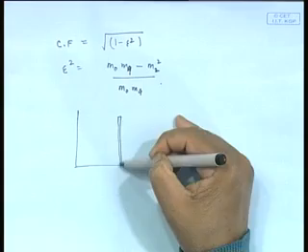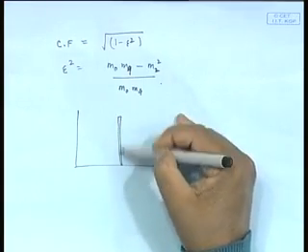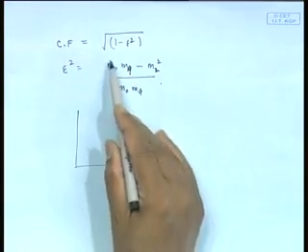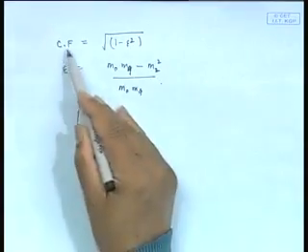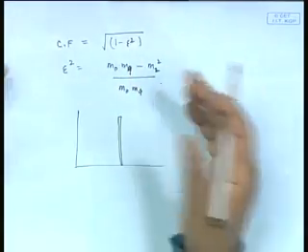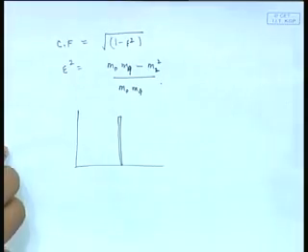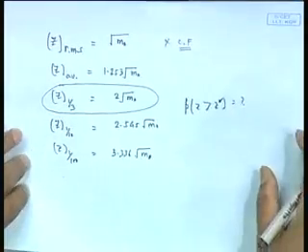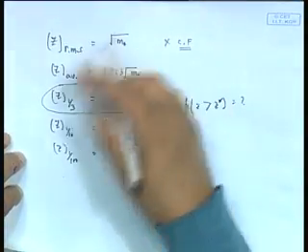And what I was trying to tell you is that if you take a theoretically completely narrowband spectrum, which means a stick, something like that, you will find out that this quantity becomes equal to 0, meaning CF is equal to 1, which tells you that for an absolutely narrowband spectrum, there is no correction. The further it goes from that, there is some correction. Sometimes people use it, sometimes people do not. The value will lie between 0.9, 0.85, etc., typically for a spectrum. Sometimes you may want to use it, that is all. So, with that you can get this number. So, what is happening? You are getting all these numbers that you want in terms of area.